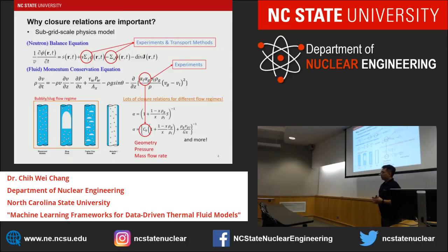But for non-Newtonian flow, the viscosity model could be correlated to the velocity. So in this case, we cannot separately train the viscosity model and then put it back into the equation, because that will cause data-model inconsistency. In this case, type 3 machine learning will have the advantage. But for problems where the scale separation is valid, type 1 machine learning will probably be good because it will cost less.